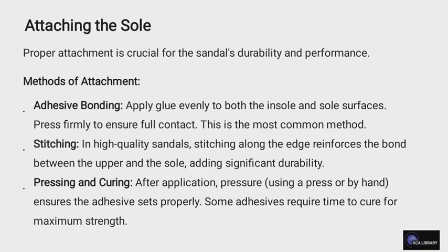Another is the stitching method, used in high quality sandals. Stitching along the edge reinforces the bond between the upper and the sole, adding significant durability. The last method is pressing and curing, where after application, pressure is applied using a press or by hand to ensure the adhesive sets properly.